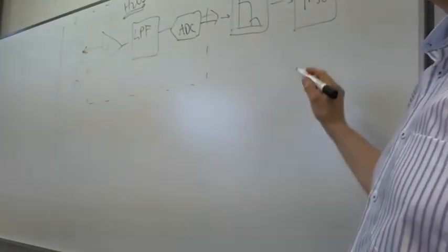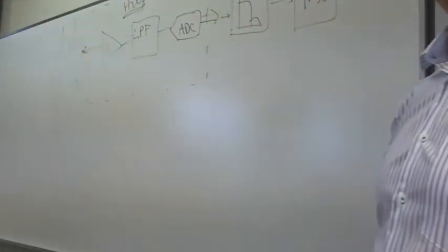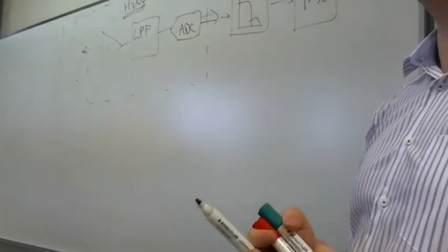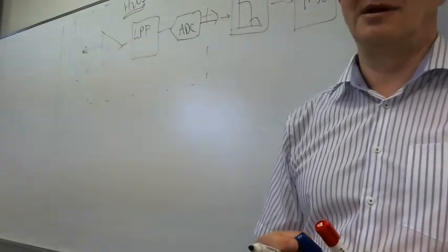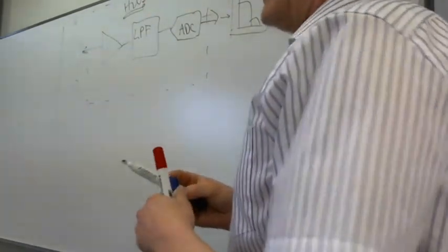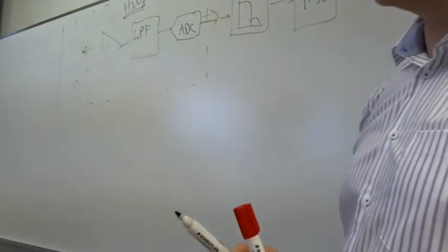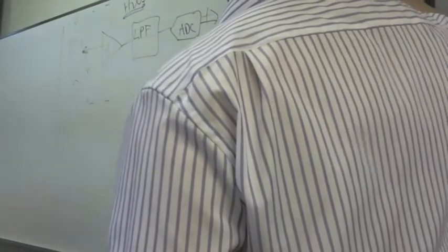Okay, but we will do a shortcut, since otherwise it might take a little bit too long. But if you already have knowledge of how to do low pass filters on small embedded systems, be my guest. Go ahead, do it. It is doable actually with the PSoC 1. You can do up to fourth order at the sampling rate we have there. It has been done. All right, and then just display. Yes, downsampling.